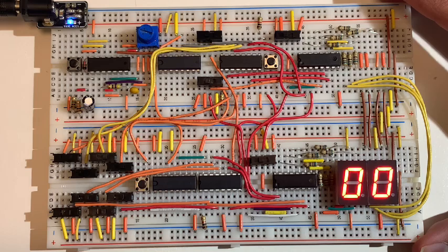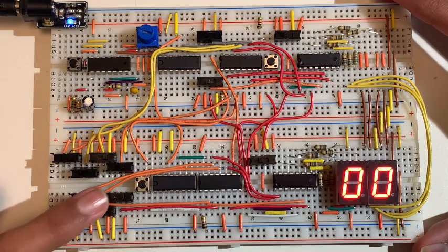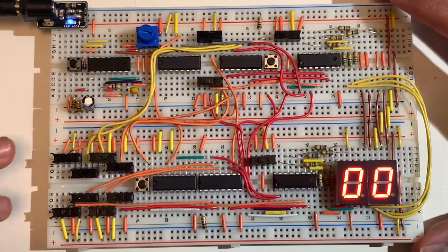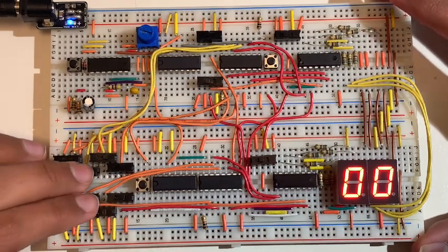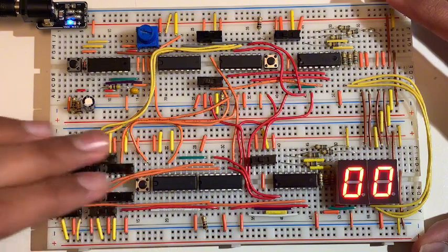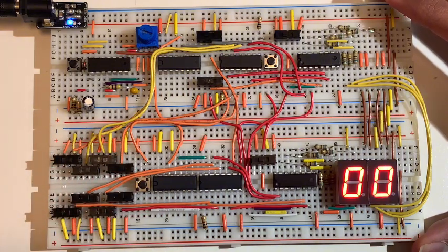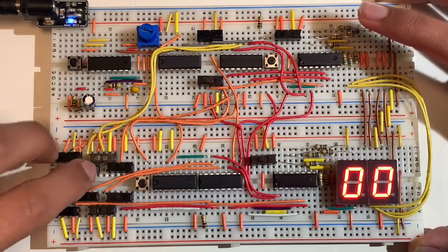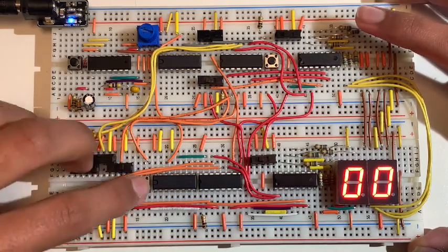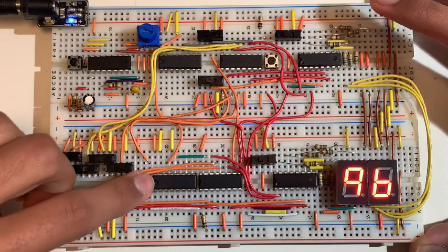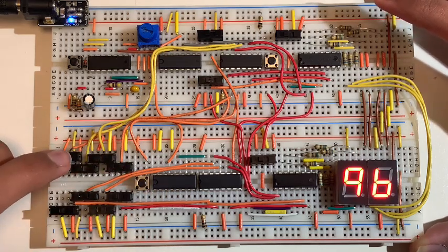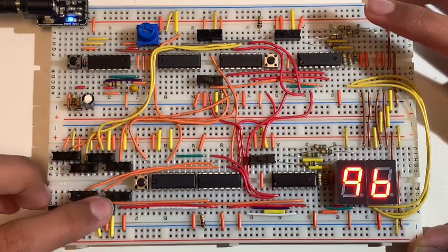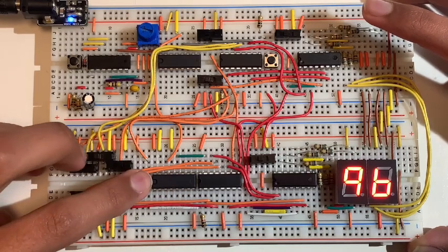Each input pin of both ICs is wired to a slide switch representing a binary value, with the preset pin connected to an active low button. The preset switch values are 8, 4, 2, and 1. To preset, for example, 96, set the tens digit to 9 and the ones digit to 6. Pressing the button will then display 96. If the value on the switches ever exceeds 9, so for example, 11, the display will turn off.